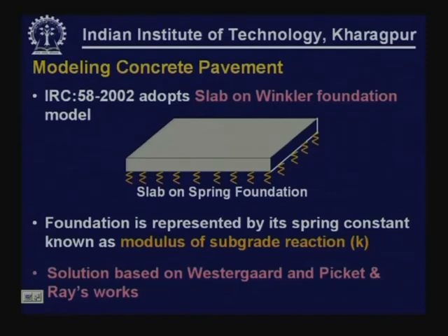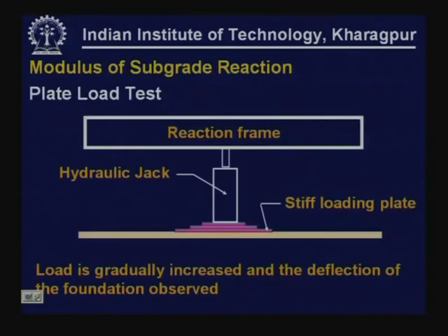The analysis of concrete pavements, or the solution of these problems, is based on Westergaard's analysis and Pickett and Ray's works. We just mentioned that the modulus of subgrade reaction is the parameter used to describe the foundation for concrete slabs. As we have discussed in earlier lessons, it can be obtained by conducting a plate load test on the foundation.